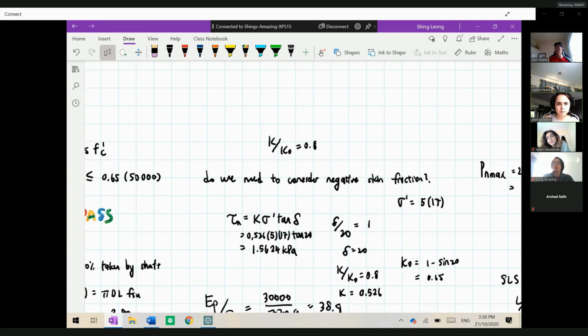I would use the, similar to the sand. Sorry, I'm trying to change it to drawing. Alright. For sand or for clay? Because the drained properties of the clay behave similar to the sand material. Sand always behaves like a drained material. So like this equation? Yep, correct. So you are going to use that to get the downdrag, which is causing the pile to be pulled downward.